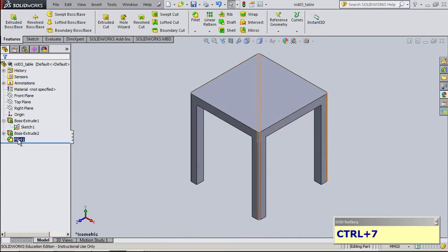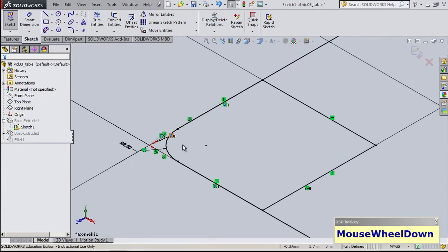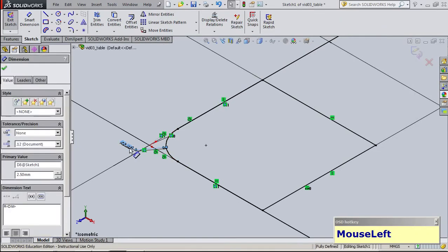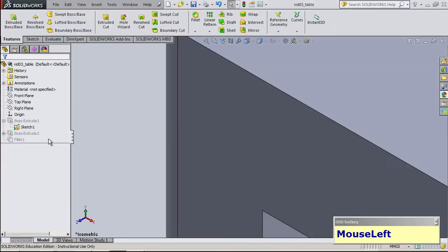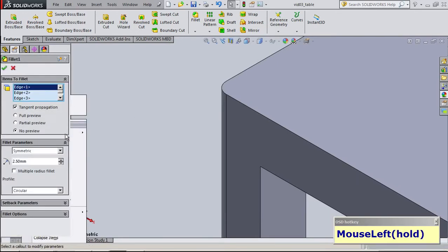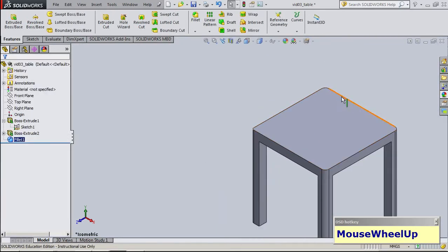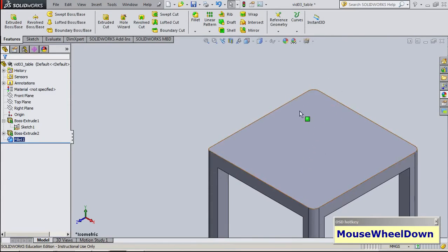and this fillet, but conceptually it's a little bit different. Because if I wanted to edit the fillet that I created on the sketch, I need to go back to the sketch and manually edit this particular diameter. If I, on the other hand, wanted to edit the fillet here, this is actually a feature on the geometry. So if I just right click here, edit feature, and then go from here to say 5 millimeters and then say OK, notice that all of the other fillets get updated. This fillet gets updated.